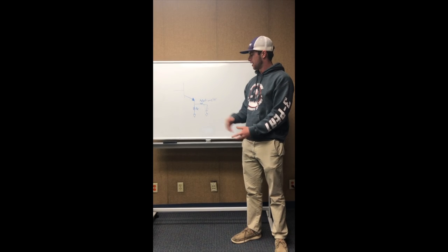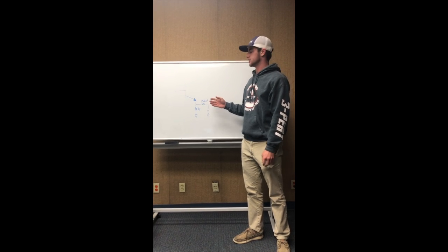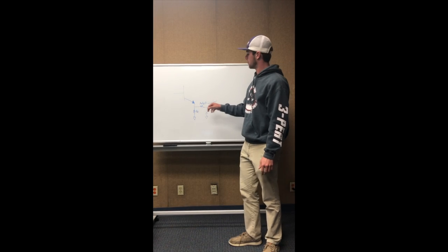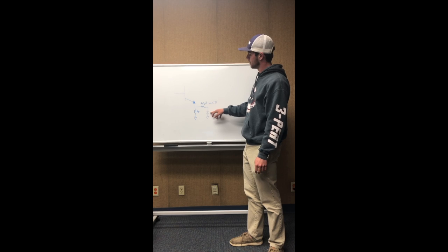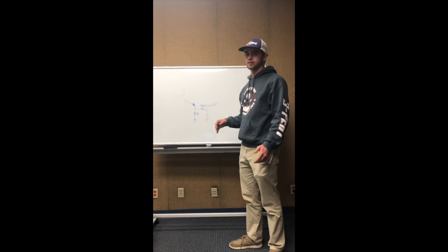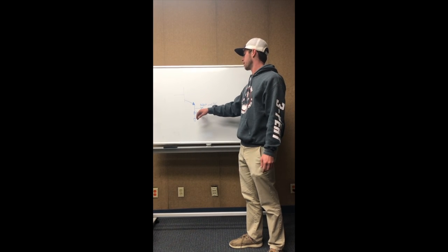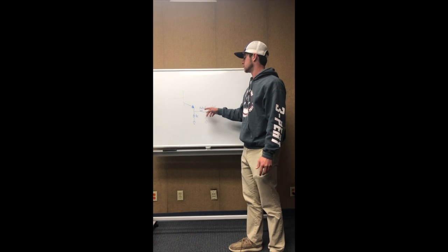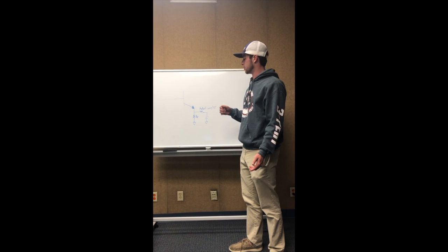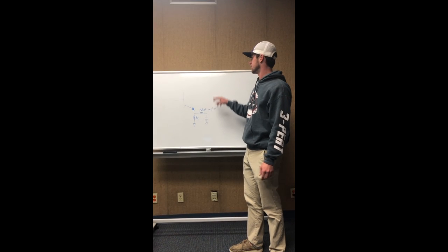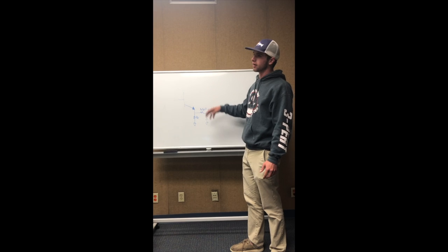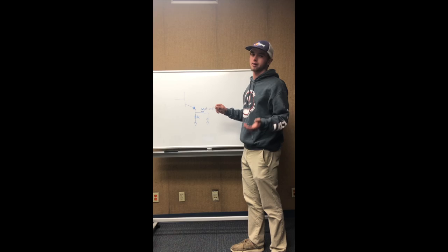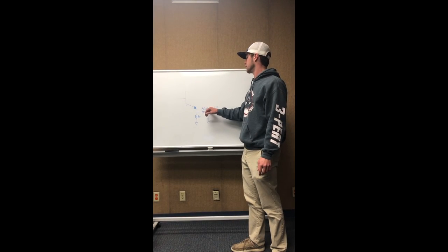Alright, so here we have our emitter part of our transistor, and we're going to look at what a potentiometer could possibly do to the circuit. So we have our RE potentiometer and our capacitor here. What the potentiometer does is it changes the resistance, and it's in parallel with RE. So if we make this 1 ohm, these two in parallel is going to be 1 ohm or less, meaning that our gain is going to be huge. If this thing's something like 20K, our gain is going to be huge. But we can also make this really big to make our gain smaller if we want, and we can change the gain. That's what that's going to do.